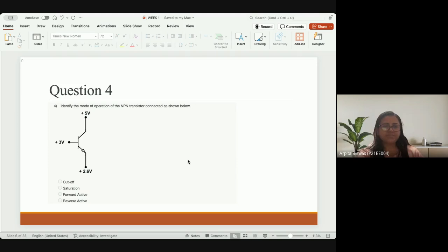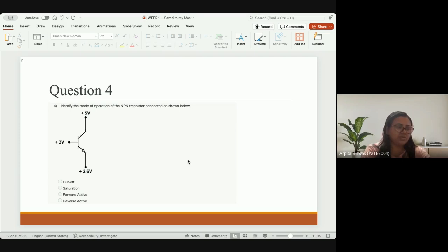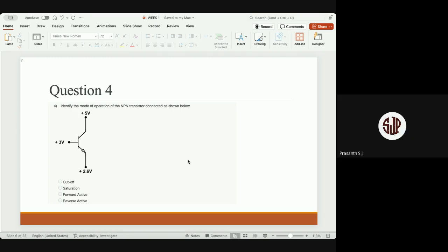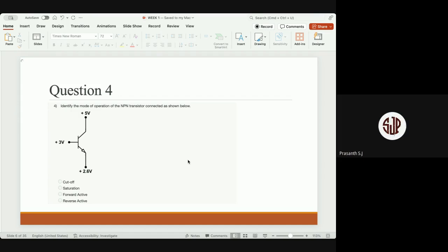Okay. Hari? Rishika, what is the right option? Option 3, forward active. Okay. Any of you, like Prashant, what is the right option? Ma'am, cutoff is the right option, ma'am. Okay. Rajiv, what is the right answer? Manoj? I think cutoff, ma'am. Since the VBE voltage is less than VCE, it is in the cutoff region, ma'am.